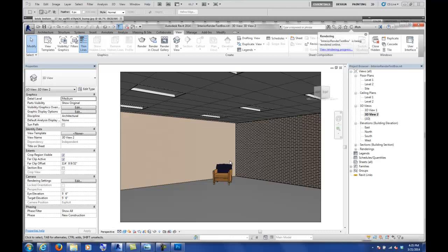The option there for the interactive panorama, that's part of that dialog box. That is a really cool feature. It's kind of left over from the 3D Studio days. You could actually export a camera view, and if you use that option as an interactive panorama, it takes a 360-degree rendering from that camera point. It then gives you either an AVI file, I think it gives you a QuickTime movie file. And so when you open up that QuickTime movie file, you can literally pan around in orbit and look around like if you were moving that camera around in 360 degrees.